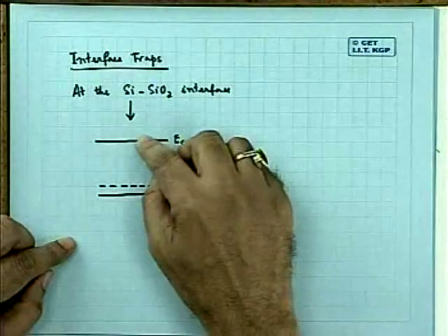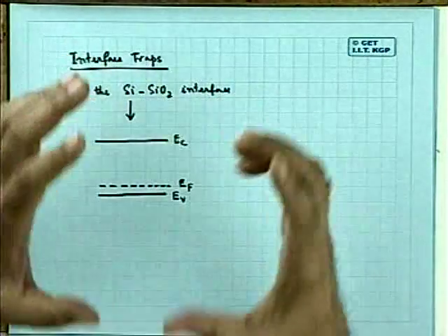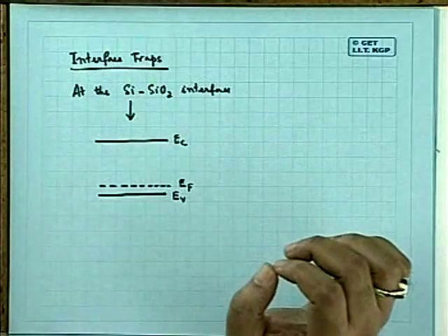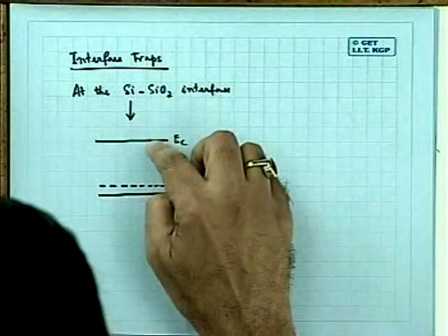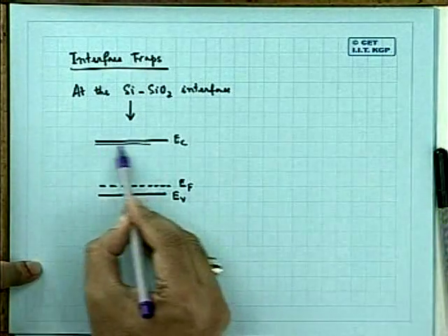It was analyzed by the physicists, and they found in such cases of semi-infiniteness, the general band structure remains the same, excepting a lot of energy states are introduced in the so-called forbidden gaps. All these forbidden energy gaps are now flooded with many energy states which are not as dense as those in the conduction band, valence band, and other allowed bands. Those are very dense and practically continuous, whereas in the band gaps there will be states, but they are not as dense as in the conduction band and valence band.